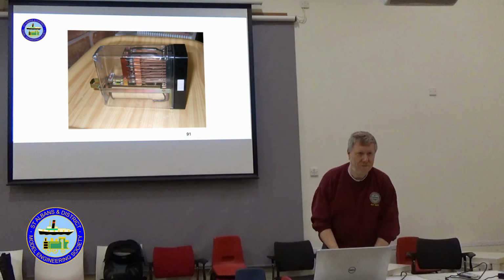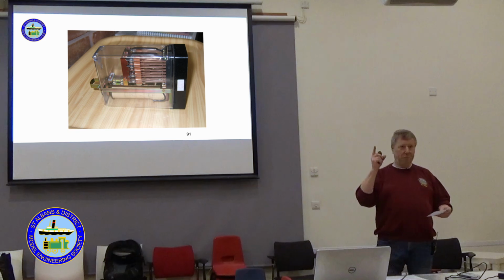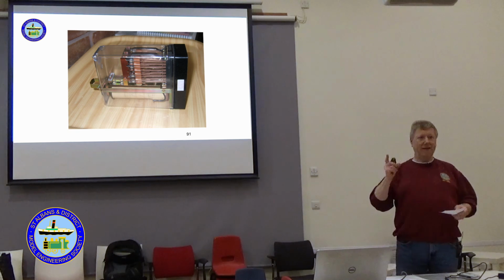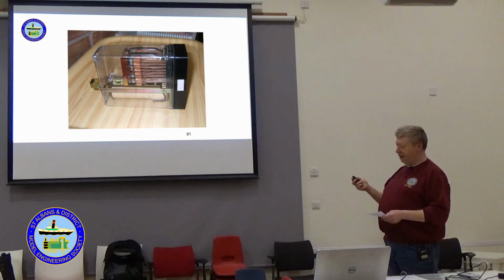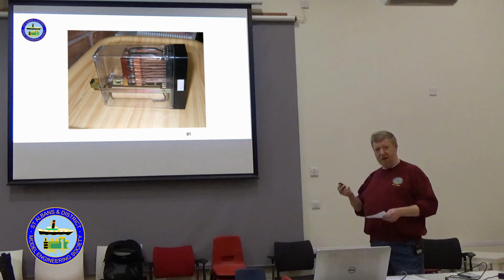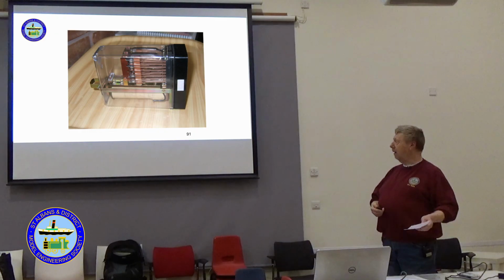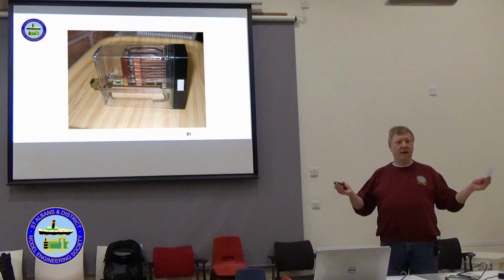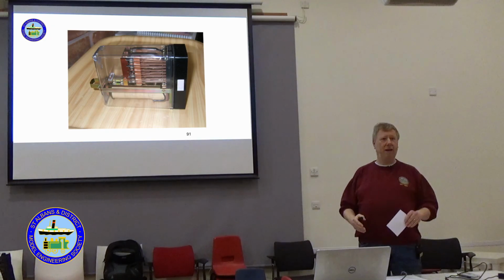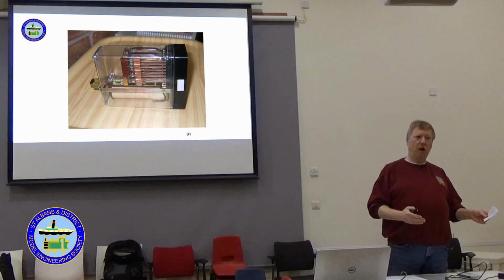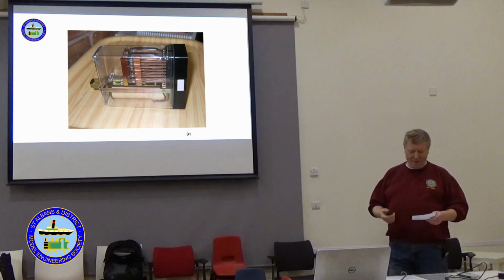They might sound a bit convoluted for something as simple as that, but the reason they do that is it's simple, doesn't fail very often. If you think about it, when you lose power, the relay de-energises and everything fails safe. It assumes there's a train coming, which is a lot better than assuming there isn't a train coming, and there is.